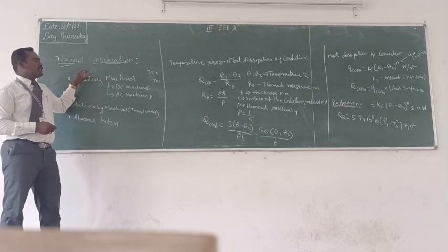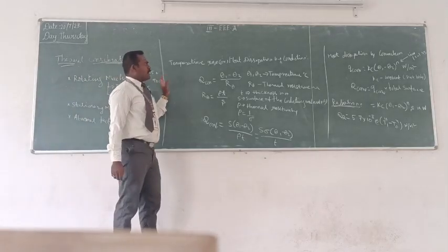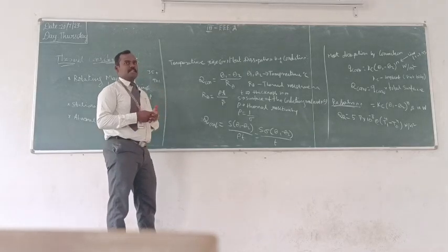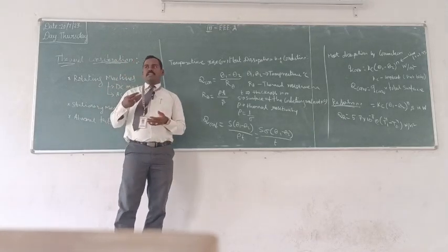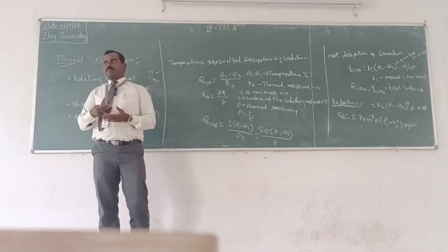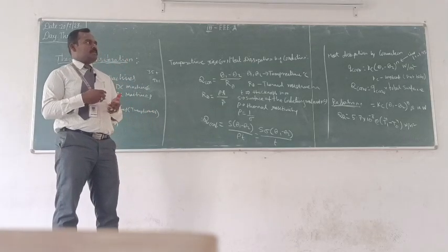That is why temperature consideration is essential. Anyhow, we can't avoid the temperature rise, because the conducting medium or conductor itself has internal resistance. The temperature increase or temperature variation we can't avoid easily, so it is a considerable factor.